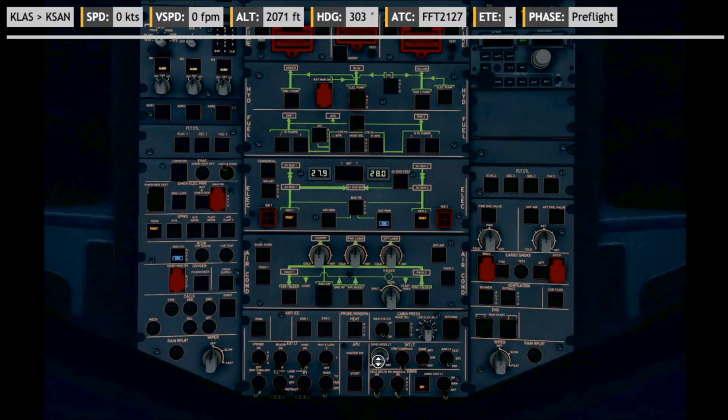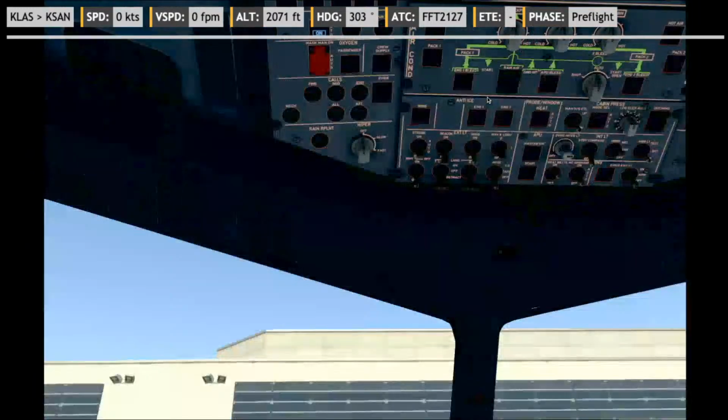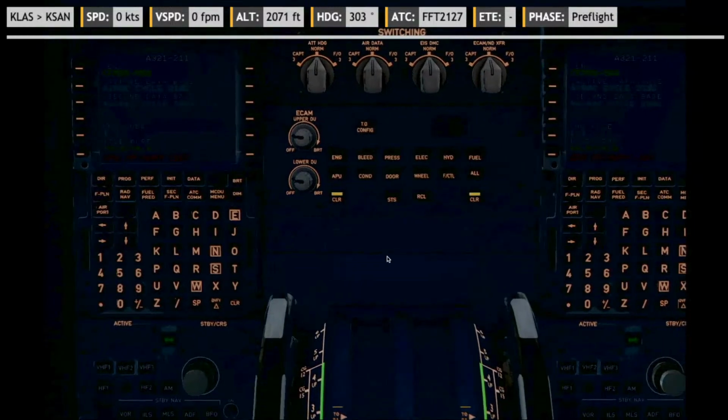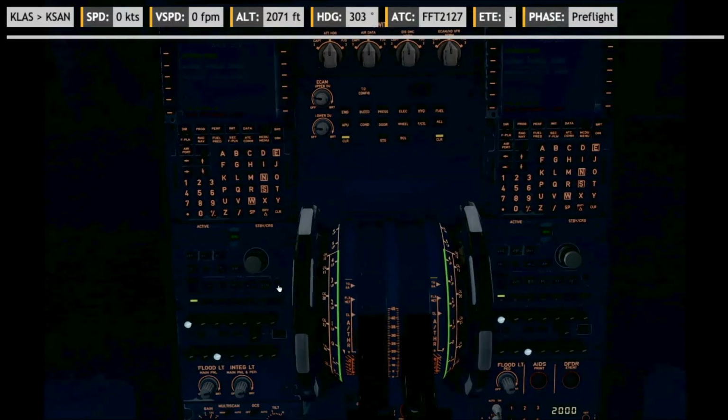Get these lights a bit brighter. Dome lights to bright. Seatbelt sign on, and no smoking sign. Auto emergency lights armed. This looks fine. Flight control computers are all fine, and let's activate our 3rd radio there. There's 2 radios in the bottom that are our primary radios, and then we have the other one down there. Alright, let's continue our setup. Get this radio on.